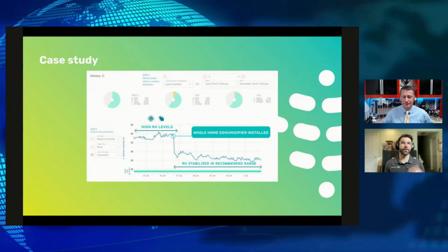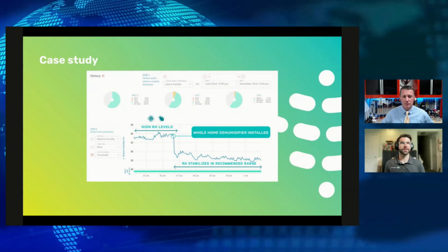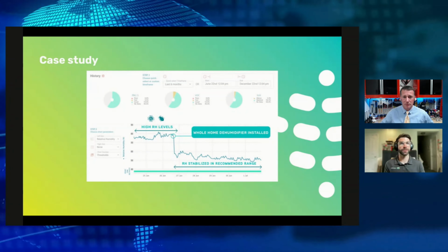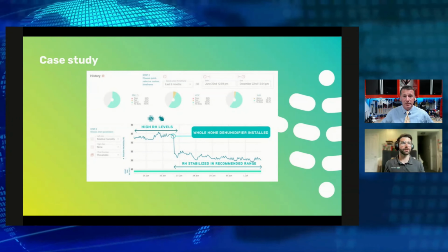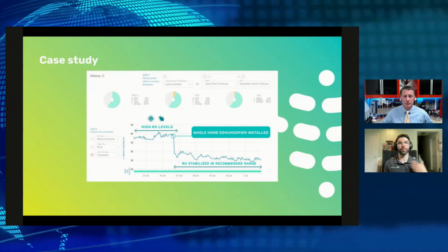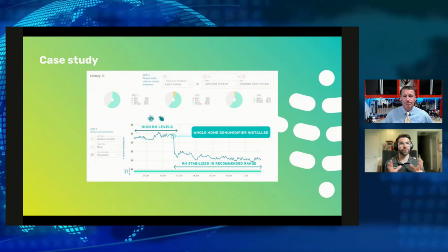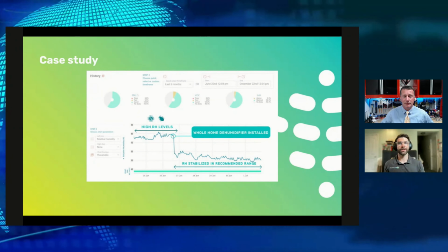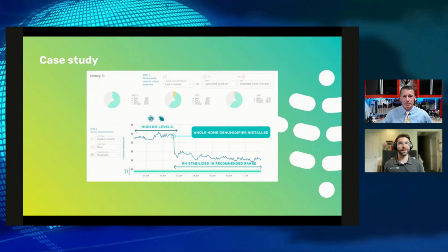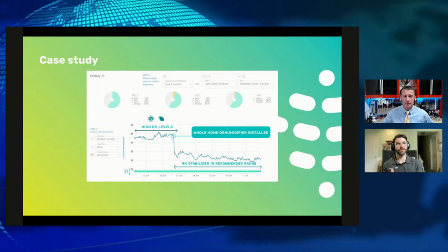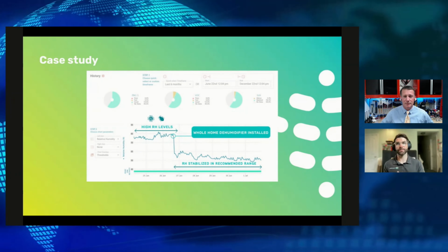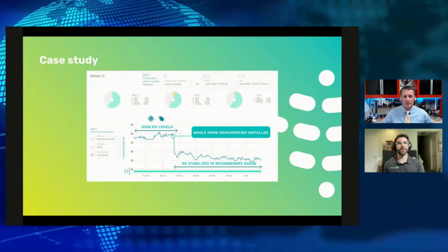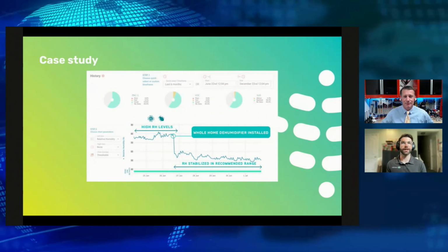And people don't think, if I had two or three of these, you're quickly in the territory where a whole home solution would have been more effective and realistic, because you're moving more air, distributing it. You have this distribution system and this fan that you've invested in, and obviously you want to design the filtration system to meet the right static pressure for the system and use the right amount of surface area to not create issues.